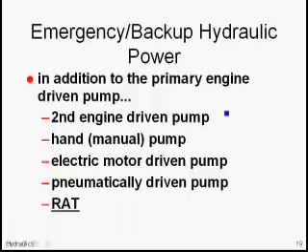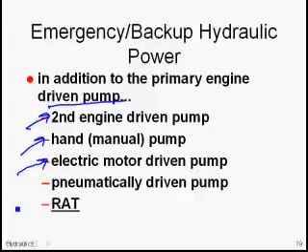Okay, there's a lot of ways to get backup hydraulic power or emergency backup power. Of course, if you've already got an engine-driven pump, you could put a second one on another engine. You could put a second pump on the same engine. Of course, we already discussed that in a 182 RG with retractable gear, you could have a manually powered hand pump to supply backup hydraulic power in case the primary hydraulic pump fails. In transport category jets, big biz jets, big turboprops that power the flight controls with the hydraulic system, you're not going to be able to produce enough power, pressure, or volume with one or two people running a hand pump. You're going to have backup electrical pumps.